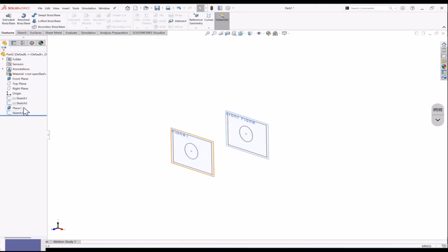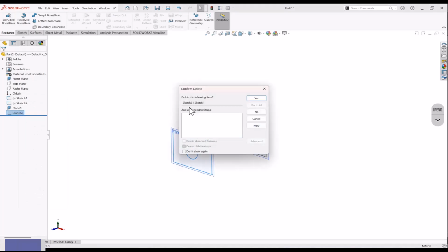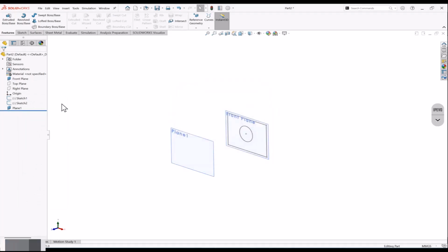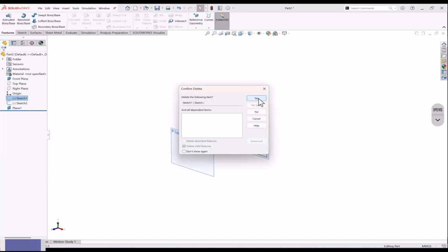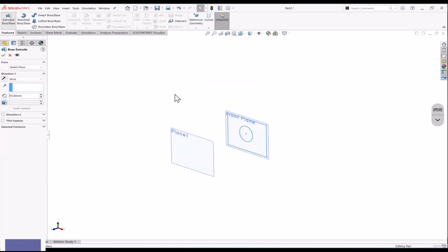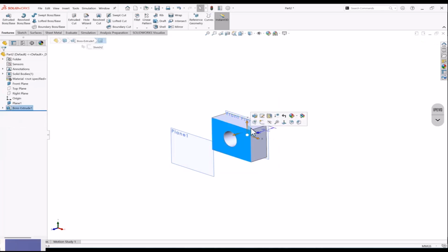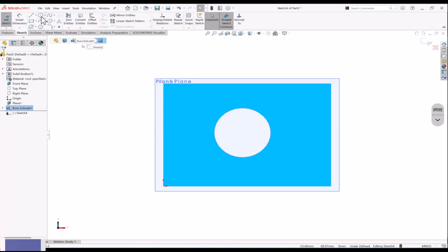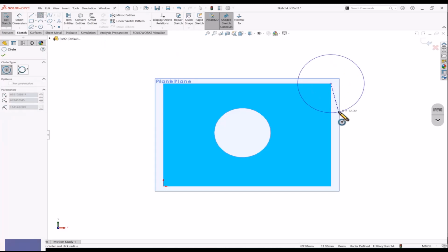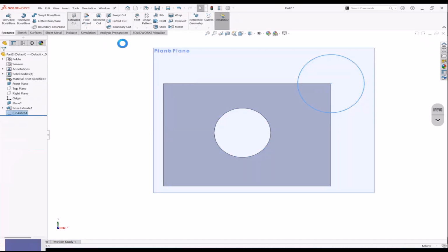Now, if I make a part, let's do one thing. Let's do some part creation. I'll just use that sketch. Let me delete the extra sketch from here and make an extrude of this. Okay, and do okay. Let's do something more. I'll just put some cutout here. Let's remove the material from here. I'll just make an extrude cut.